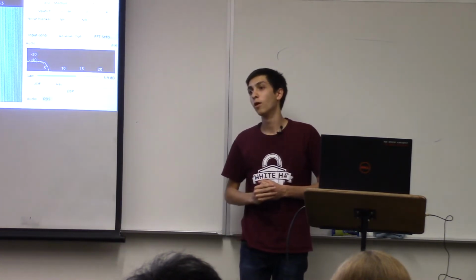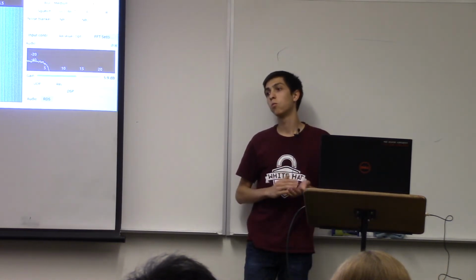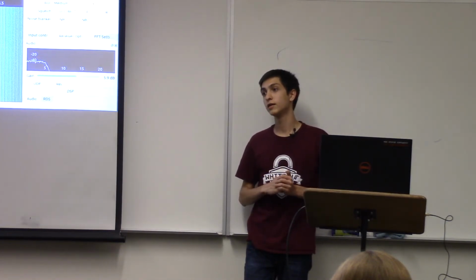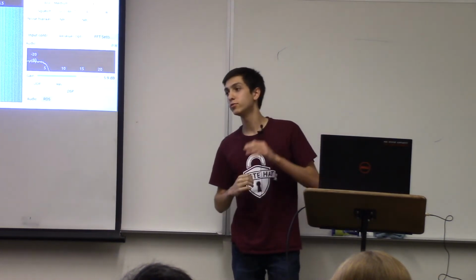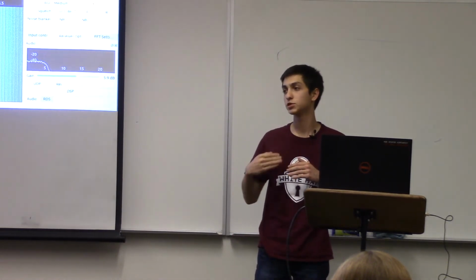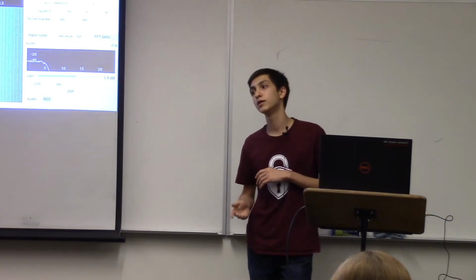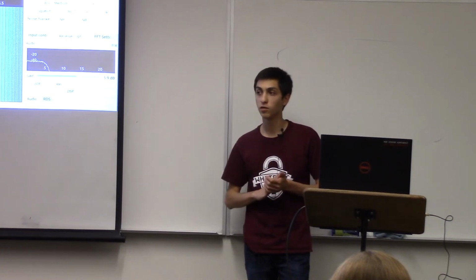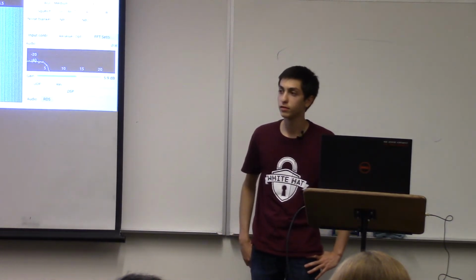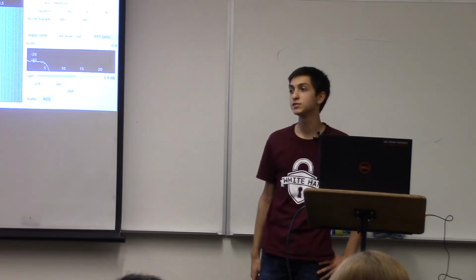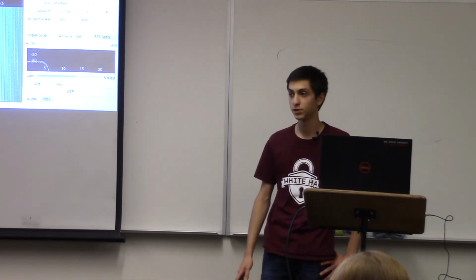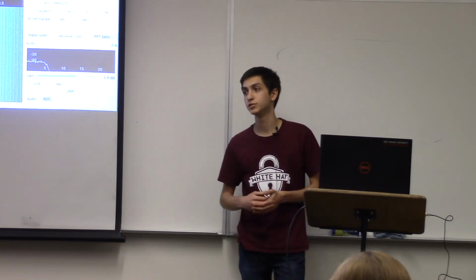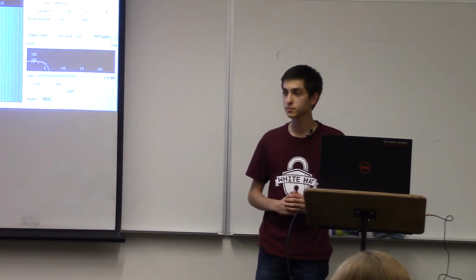It's very dependent on what you're doing, but if you don't know anything about the hardware, it gets complicated. But say you know the program, but you don't know exactly which instruction it's on, you can try to measure power usage to see what instruction matches to a certain amount of power usage, and you can do stuff like that. Also, if the device outputs something right before the thing that you want to skip, you can use that output as a trigger and then start introducing errors after that output has happened.